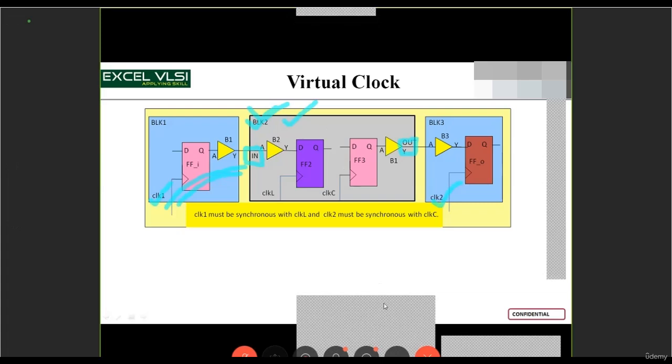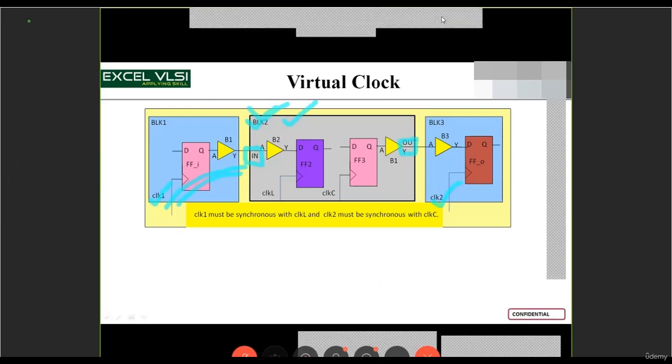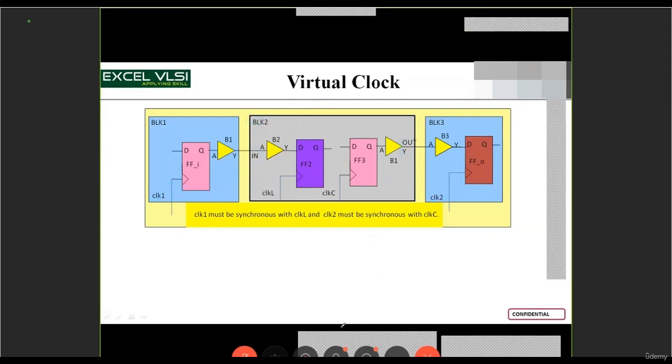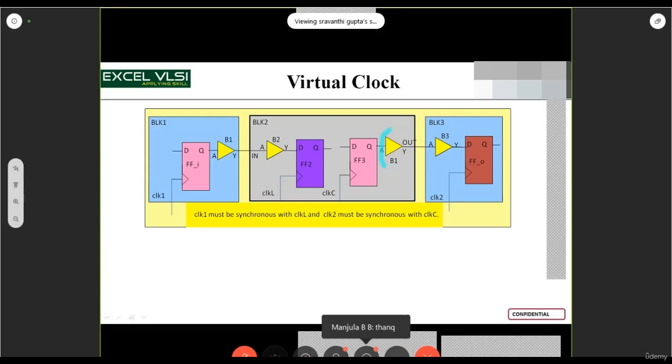Difference between slack and slew. Slack is the difference between arrival time and required time. But slew is the input transition that you're giving. Transition is nothing but a change of state, right? So that value you are giving at the input pin of the gate is called input transition or slew. Slack is the difference between the data arrival times in the clock path and the data path. When you check it in the tool, you will have a clear idea of what slack is.